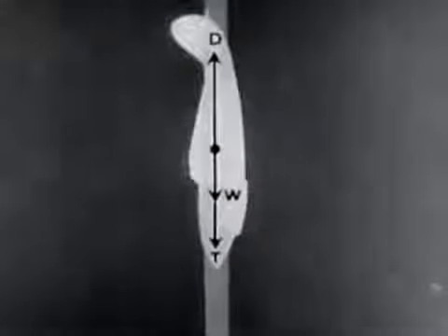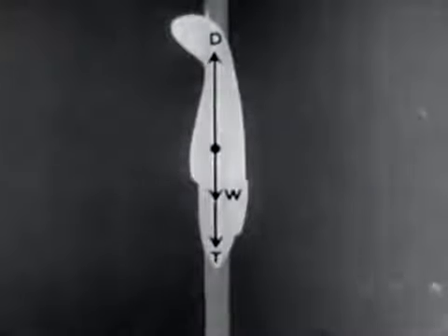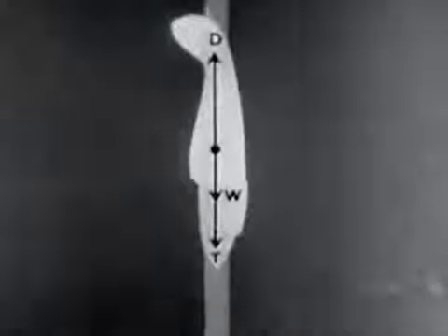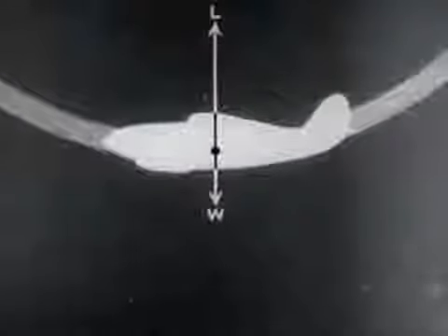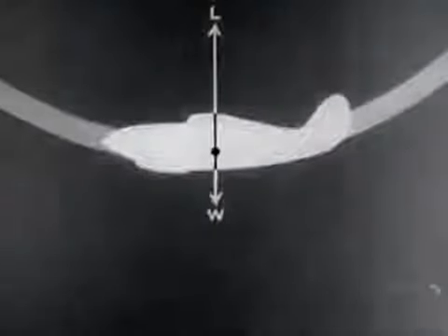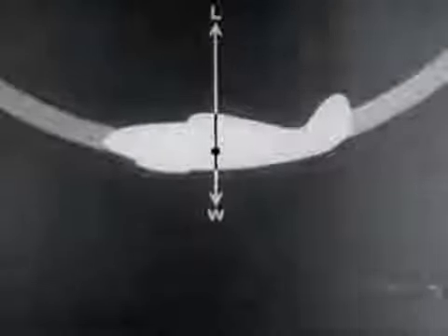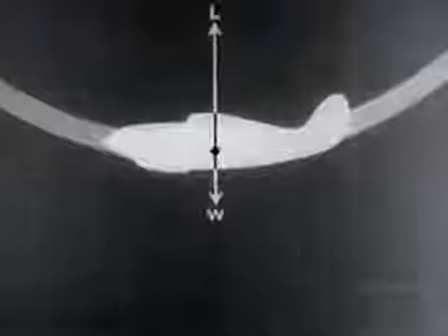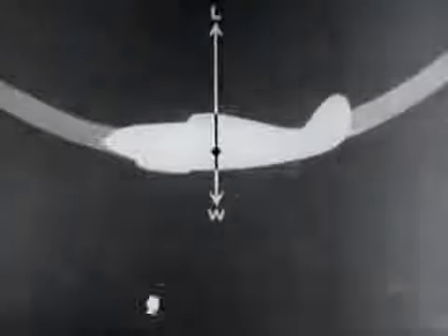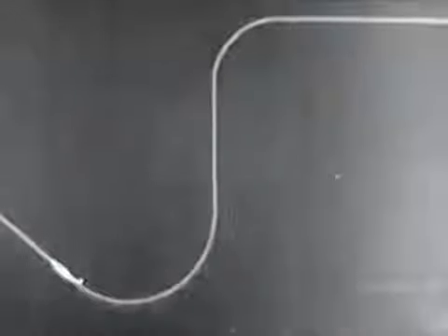In this condition, lift is zero, and the weight of the airplane plus its thrust are opposed by drag alone. In pulling out of the dive, the angle of attack must be increased slowly. During this maneuver, lift may attain several times the value of the weight. This increase in lift produces acceleration, which in turn produces a curved flight path.